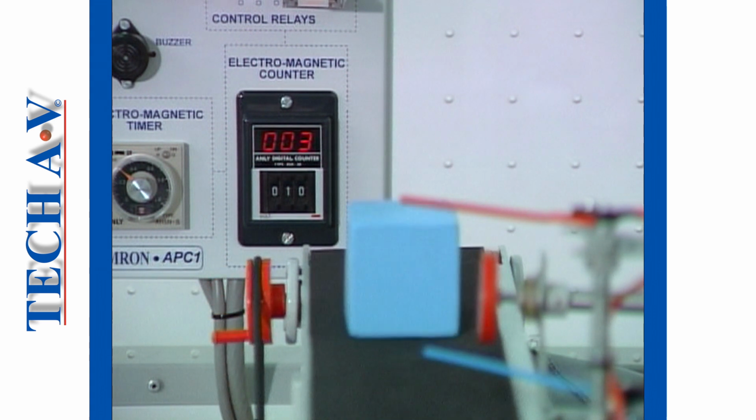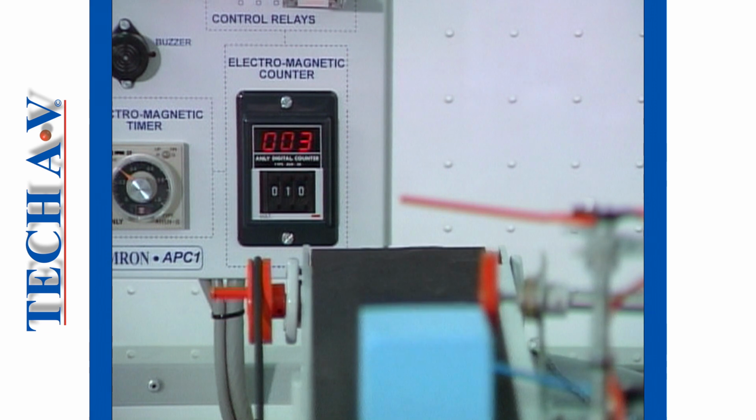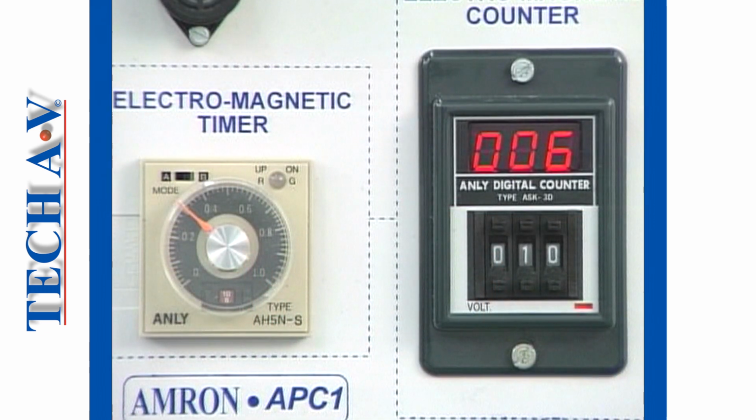When the preset value is reached, the counter's internal contacts change over to their active state and remain there, signaling the next event in the program. When power to the counter is interrupted, the count is reset to 0.